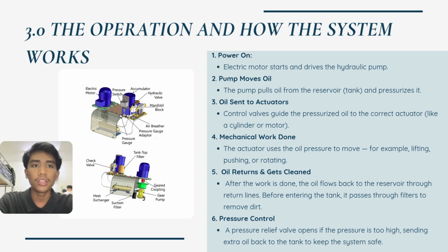Let's discuss it. The first point is power on, where the electric motor starts and drives the hydraulic pump. The second is pump moves oil, where the pump pulls oil from the reservoir tank and pressurizes it. Then oil is sent to actuators, where the control valve guides the pressurized oil to the correct actuator like a cylinder or motor. After that is mechanical work done, where the actuator uses the oil pressure to move, for example lifting, pushing or rotating.